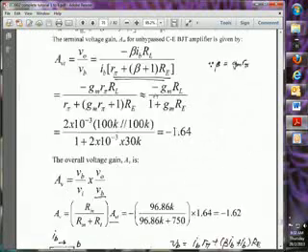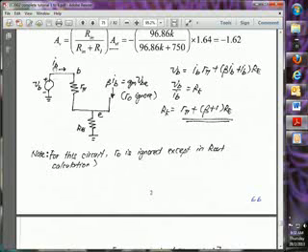With that, we get this. Note that what we are trying to find is RK, which is the resistance looking into this point, and is equal to VB divided by IB. How do you find a resistance? It's just having a voltage, identify the voltage, identify the current. Voltage VB divided by IB will give you the resistance, in this case RK.